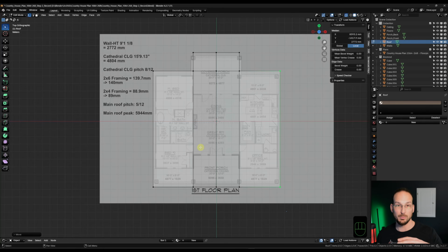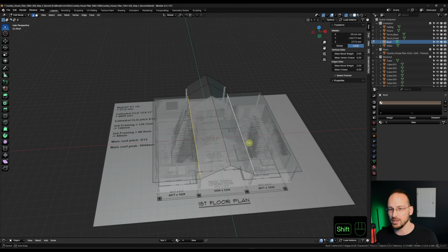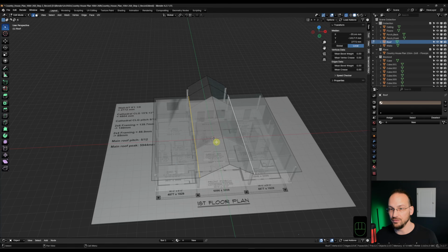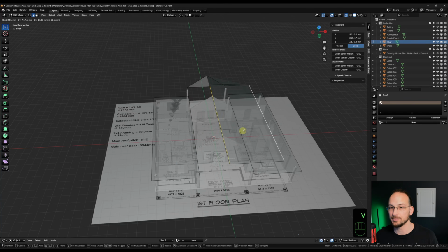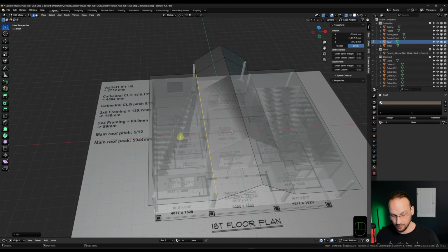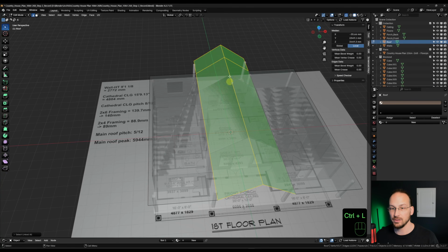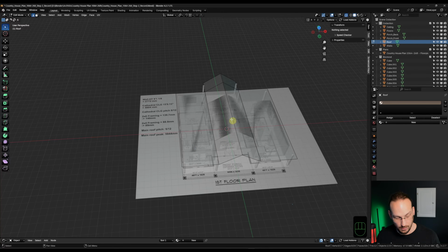As I said before, I want to build two separate roofs that I stitch together afterwards. So what I'm going to do is go into edge mode. I'm going to select these two edges here and hit V to tear them apart. Sounds brutal, but it's okay. So now if I Control L them, this one is one island and the other ones are separate. And now I can work on them separately and it makes it so much easier.